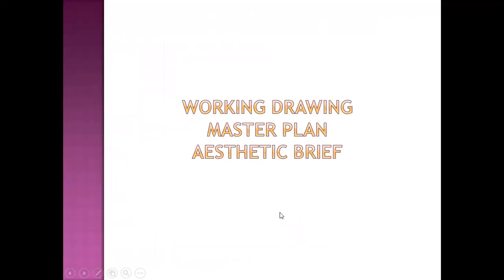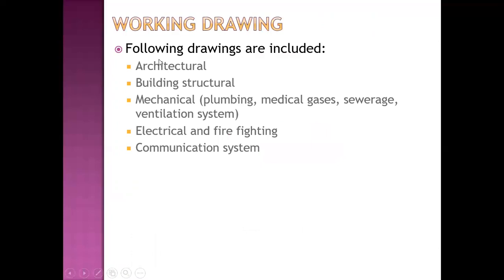Then very brief about working drawing, master plan, and aesthetic brief. Following drawings are included in working drawing, that is architectural drawing, building structural drawing, mechanical parts like plumbing, medical gases, sewerage, and ventilation system. Electrical and firefighting.